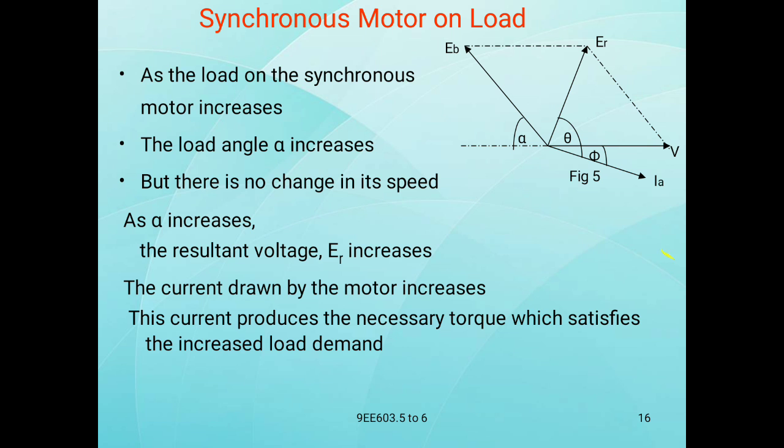Now the synchronous motor on load. As the load on the synchronous motor increases, the load angle alpha increases, but there is no change in its speed. As alpha increases, the resultant voltage ER increases and the current drawn by the motor increases. This current produces the necessary torque which satisfies the increased load demand.